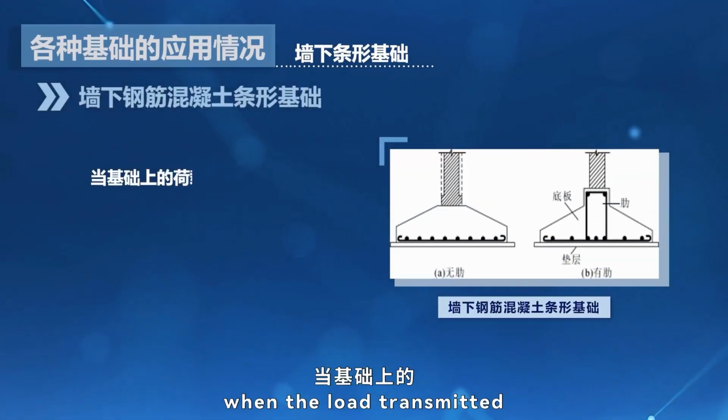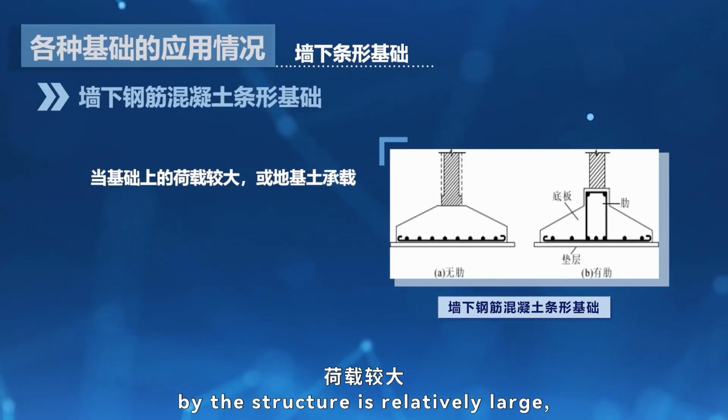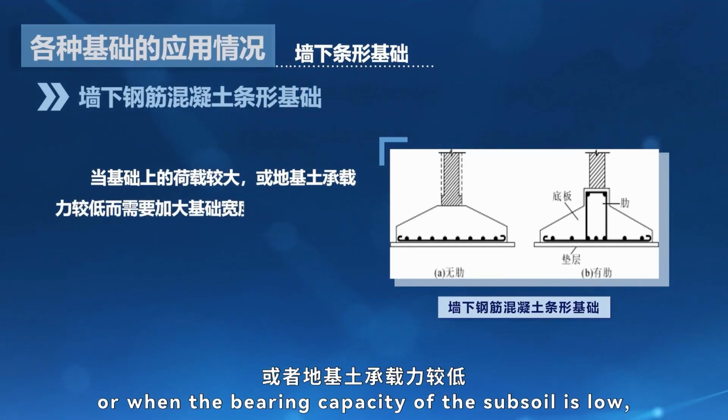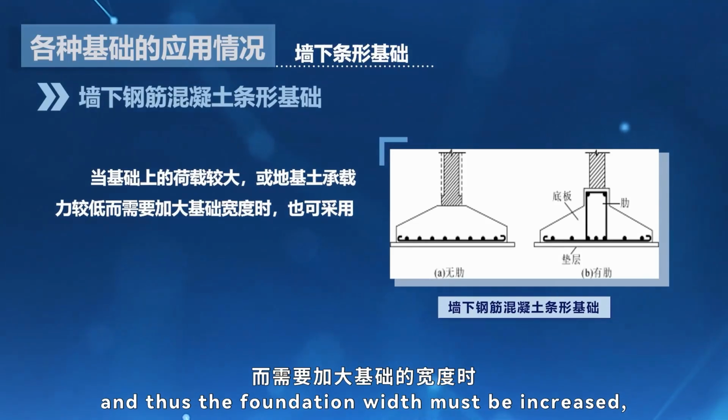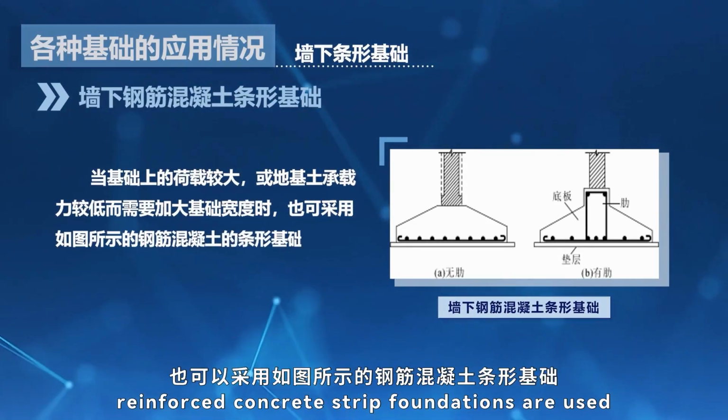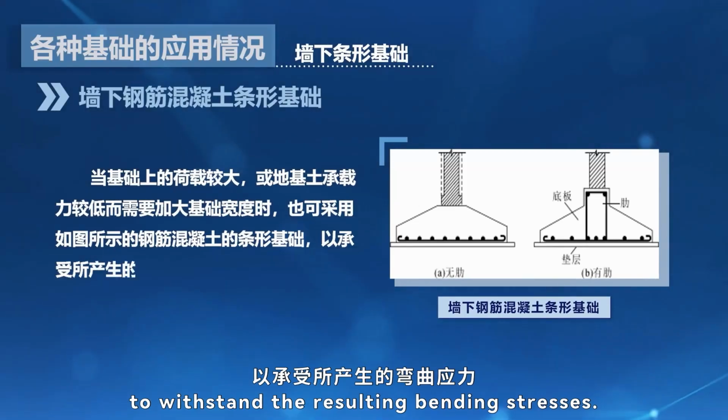When the load transmitted by the structure is relatively large, or when the bearing capacity of the subsoil is low, and thus the foundation width must be increased, reinforced concrete strip foundations are used to withstand the resulting bending stresses.